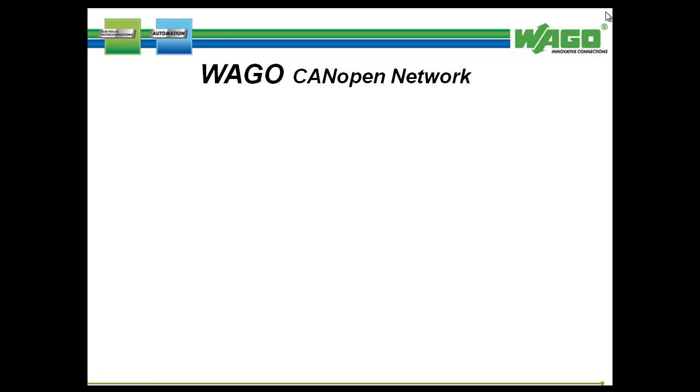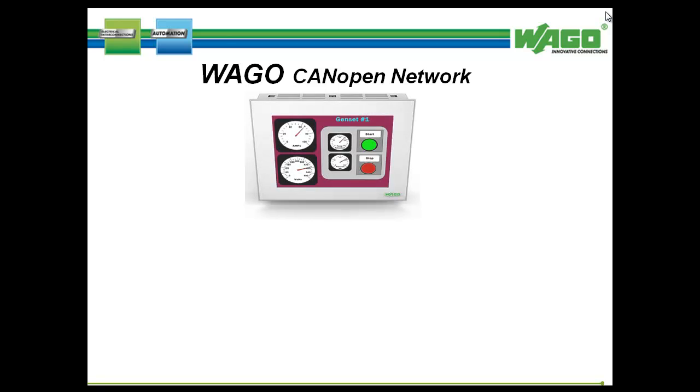In this video, we're going to cover working with the WAGO Perspecto CP TV panels and configuring a CANopen network. With these panels, you have CANopen Master functionality. It has two options with regards to the CANopen ports, a D-sub connection or an RJ45 connection.